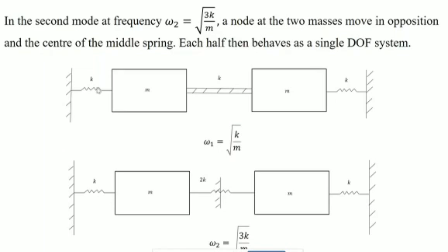And then as a whole, if I try to see what is the equivalent stiffness, then it should be P divided by K equivalent. So P by K equivalent equals P over K1 plus P over K2. If you cancel P from both sides, you get 1 by K equivalent equals 1 by K1 plus 1 by K2.